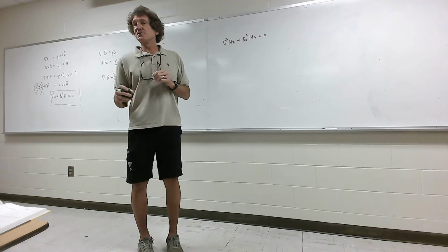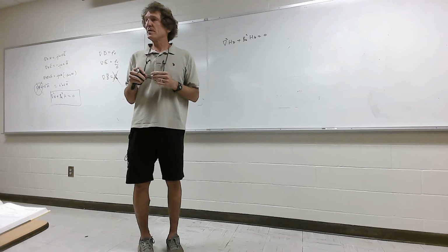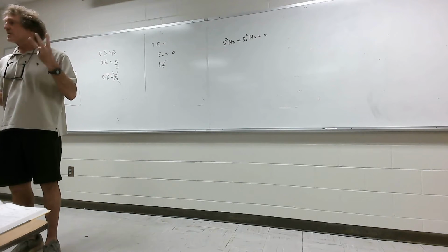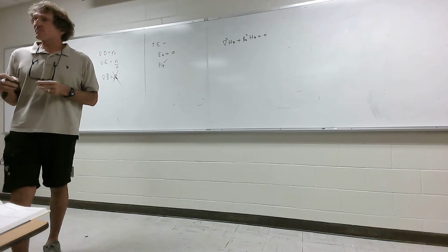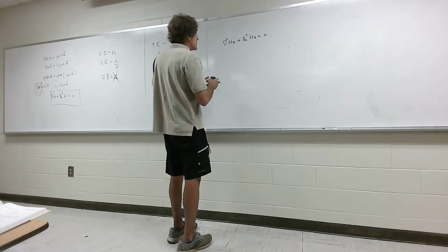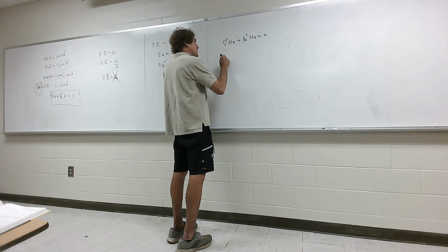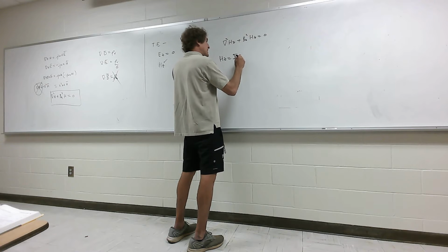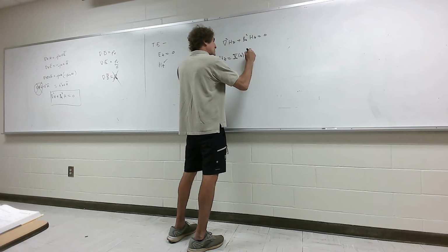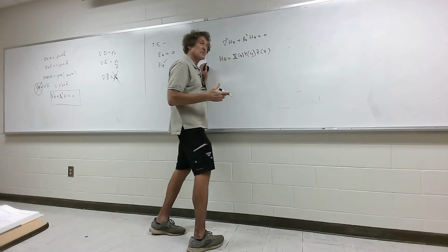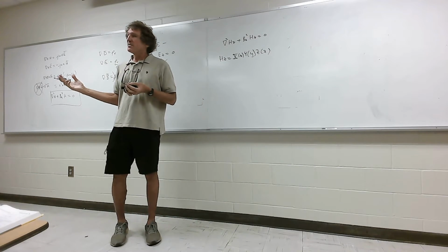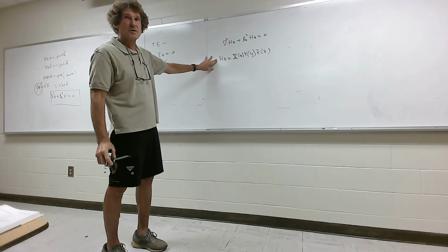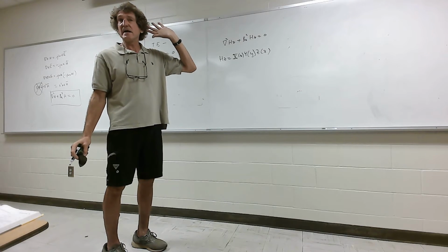Now, we're only going to do the HZ component. Remember, in general, the E field and H field both have 3 components, and that means when you do a del squared operator, you're going to have 9 total terms if you do it right. But for this one, we're going to assume HZ itself, using separation of variables, can be written as some function of X, some function of Y, and some function of Z. Do you remember doing this? This is standard separation of variables. Then we plug it in here, and we're assuming this is just the HZ component. We're not messing around with the HY or HX component yet.